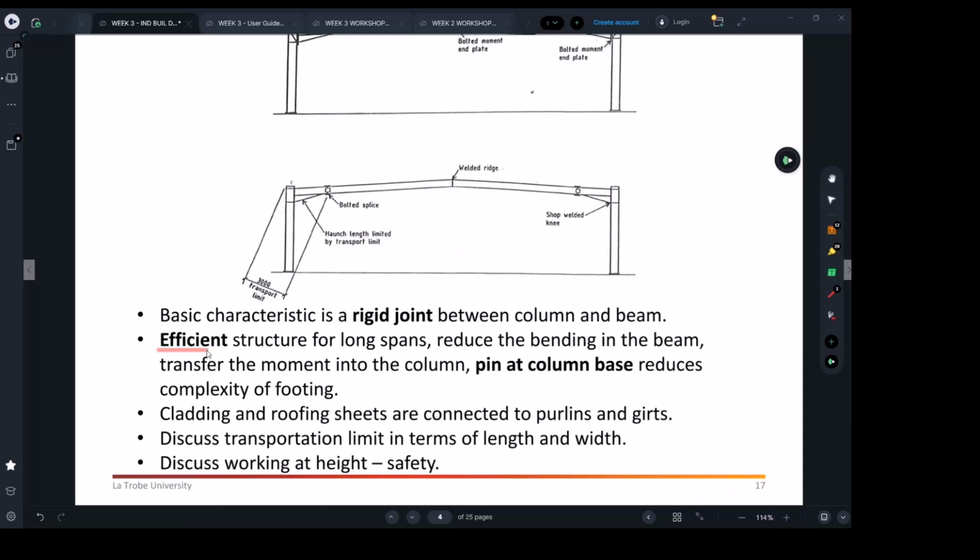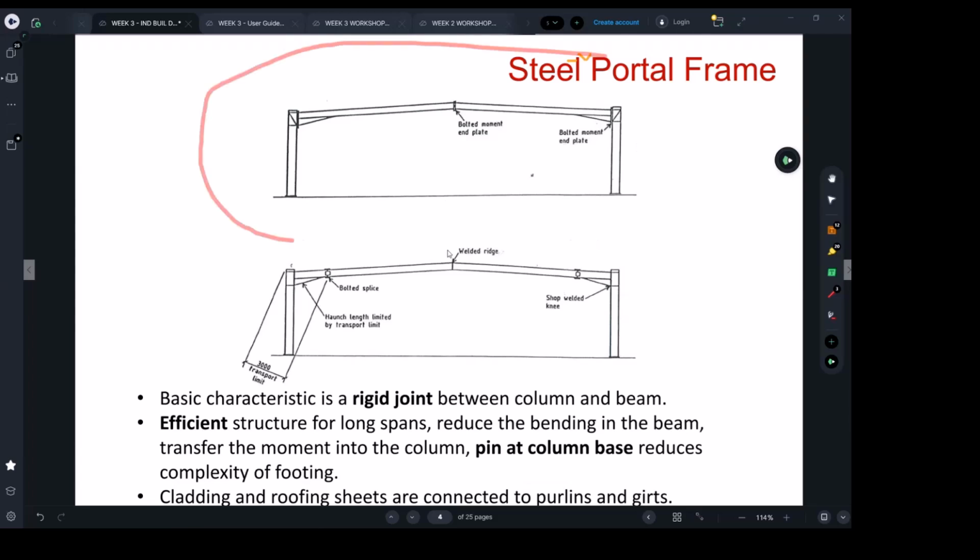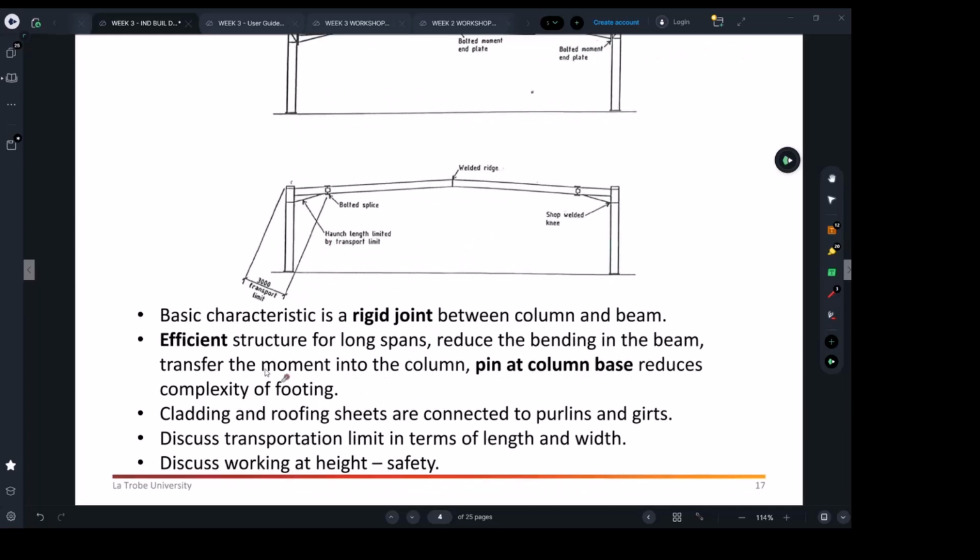Okay. And as we're saying here, to build those structures efficiently, we don't need to spend a lot of money making rigid connections. We're just going to do pin. And as you remember yesterday, a pin can be just on-site: a drill, and epoxy, just use chemicals. So you pour the footing, the gray concrete footing in the ground, and you just bring your column and then just make holes. And that's it, on site. You don't need to prepare the cage, which I showed you in another example.